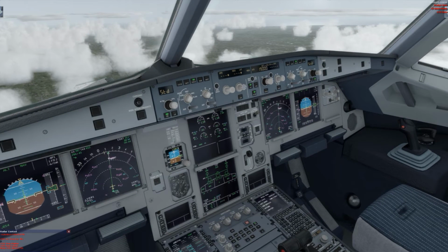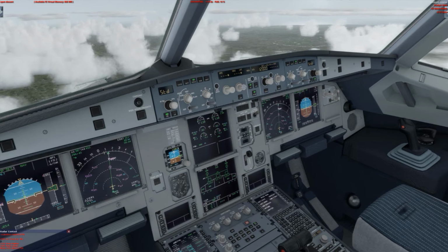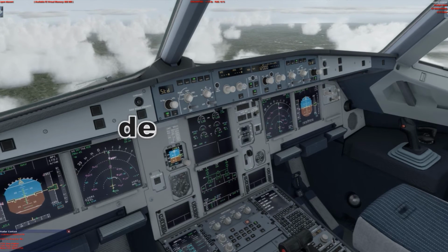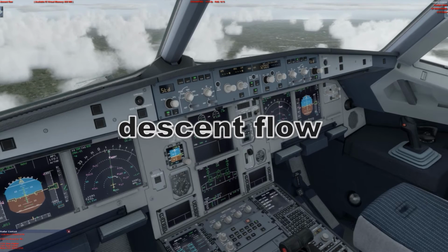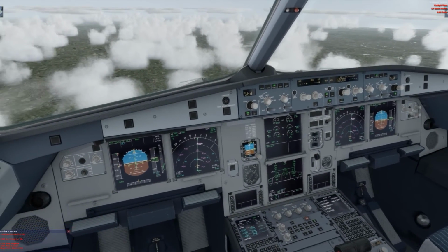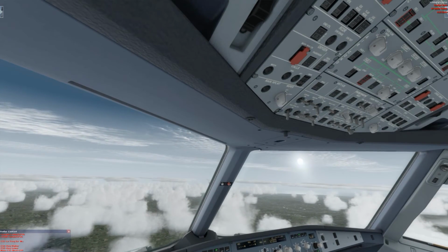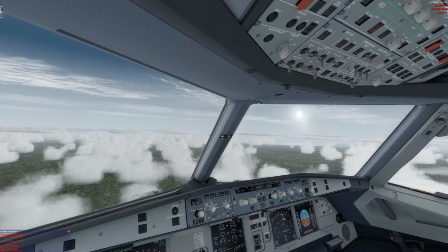Set flight level 120. Good morning. Okay, setting flight level 120. EG076, thank you. What's your requested level? Done. Open descent selected. Descent. Idle thrust, open descent. Roger. Climb flight level 330. Seatbelt signs selected on. No smoke lights switched on. Landing lights selected on. Auto brake is set to medium.